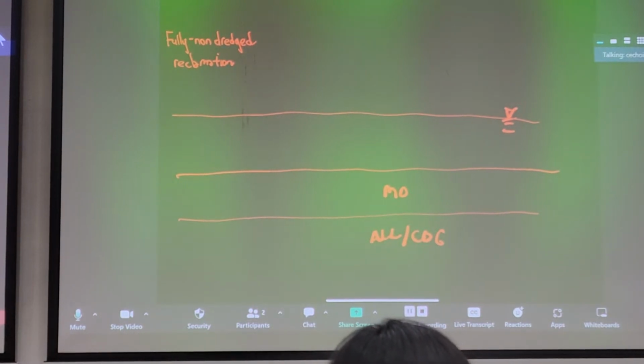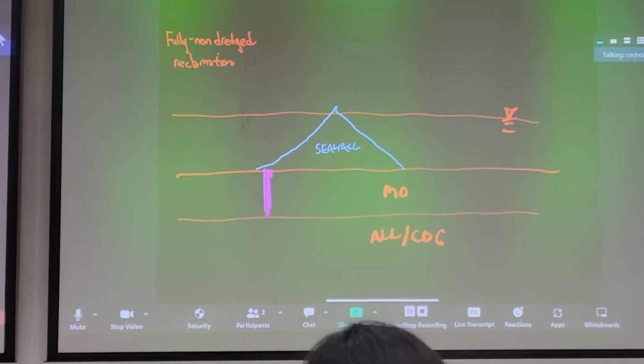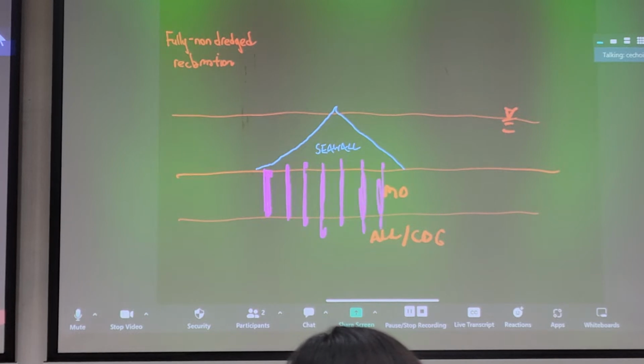So what we can do instead is try to just build some sort of seawall on top. Now, you can probably see immediate problems here with the seawall. It sits on MD, which means it's highly compressible, it's very weak. So what can we do? Well, this is where, in some applications in Hong Kong, we can use stone columns. So before we put the seawall on, we can sink some stone columns in this MD layer here. So it serves as a composite foundation, and then we place our seawall on it.